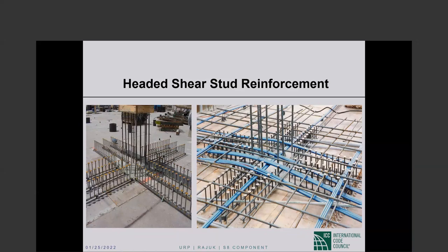You get the picture, I'm sure. Okay, so these are the stud rails. There are 8 rails used here at an interior column, and this is a situation where post-tensioning ducts have been placed. The structural integrity reinforcement that I was discussing the other day, you see the post-tensioning cables going through the column cage, and it goes underneath the perpendicular cables. All of that is illustrated here.